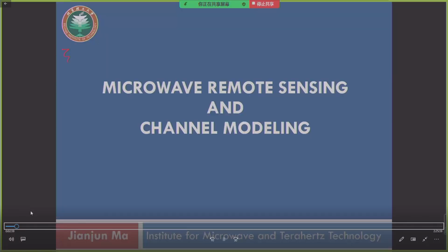The monostatic and the synthetic. And usually we consider the propagation speed of the electromagnetic waves in free space, which is the speed of light, 3 times 10 to the 8 meters per second. So the received signal consists of the sum of the echoes from the different areas within the antenna range, and also the Doppler information. So really we use the range discrimination and the Doppler shift discrimination to achieve our recognition of the object on the ground or on terrain.